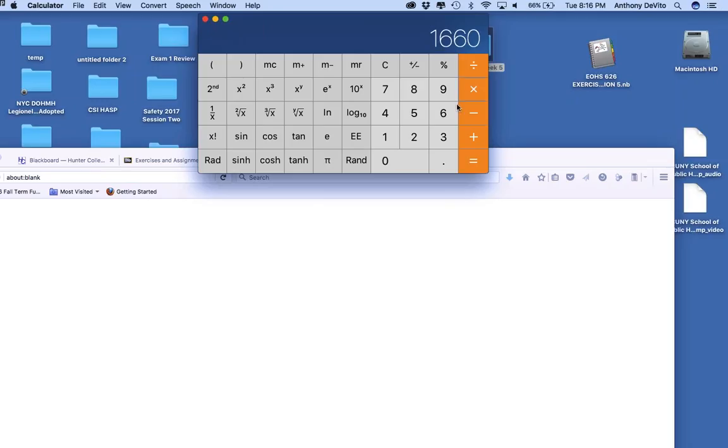I multiplied that by 60 to get the cubic feet of air per hour. It really came out to 100,000 because it wasn't exactly 100,000. And that I multiplied by 0.075 to convert from cubic feet into pounds of air. So that's the number of pounds of air per hour that we're moving through that slot.